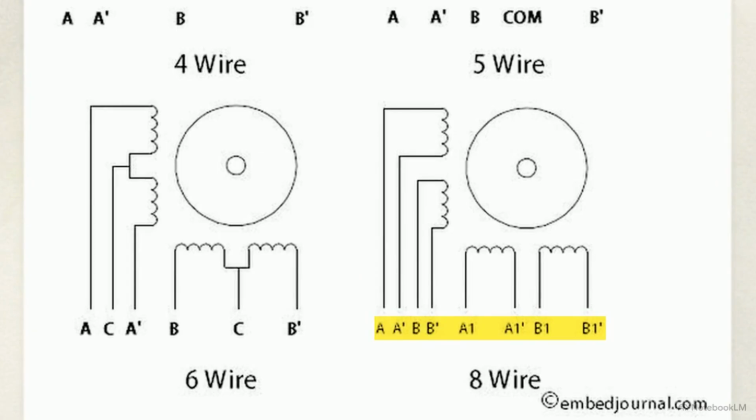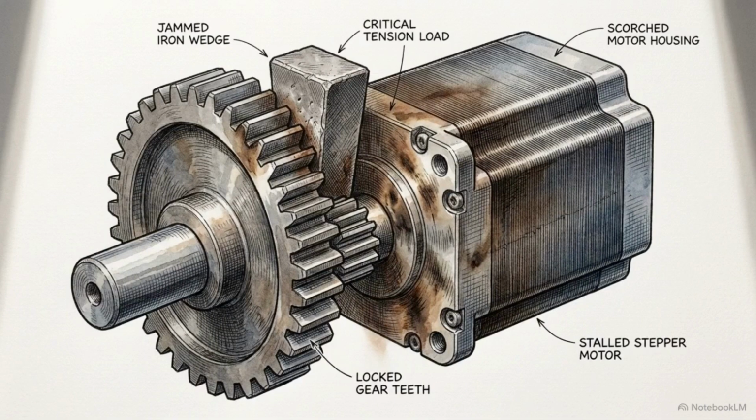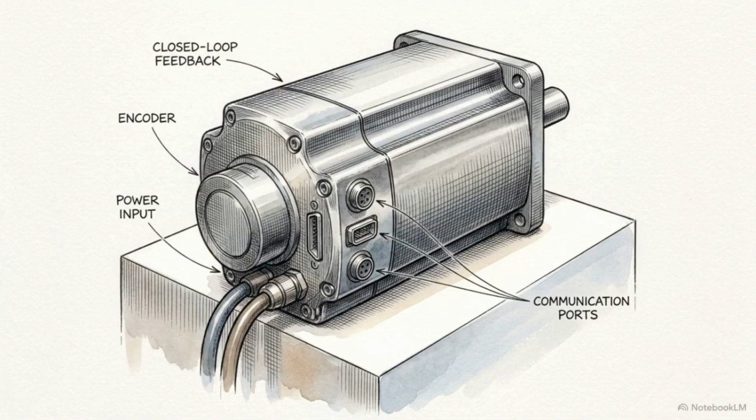This entire stepper architecture is defined as an open-loop system. The microcontroller fires the digital sequence and blindly assumes the motor executed the physical step. While steppers offer mathematically predictable precision, their open-loop nature means if physical resistance stalls the motor, the system never registers the error, creating a dangerous vulnerability. The engineering solution to that open-loop vulnerability is continuous real-time error correction.